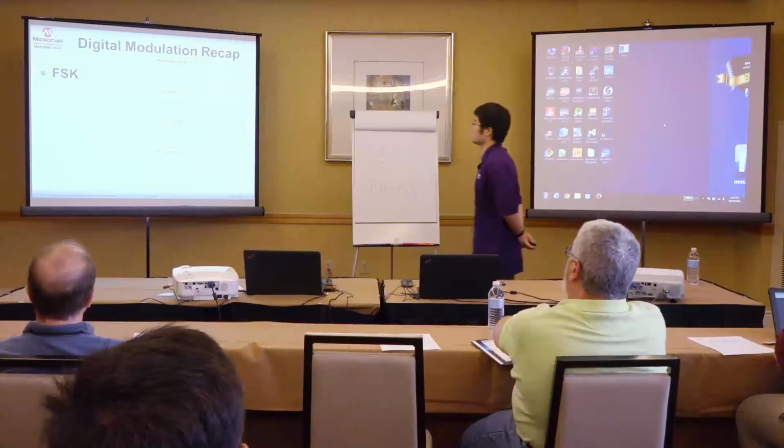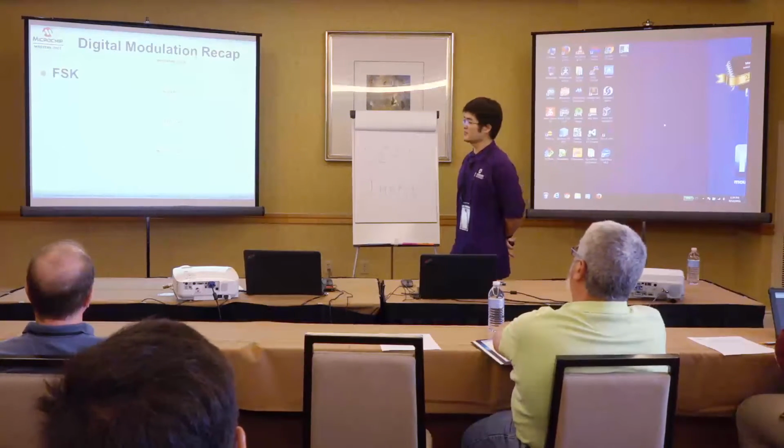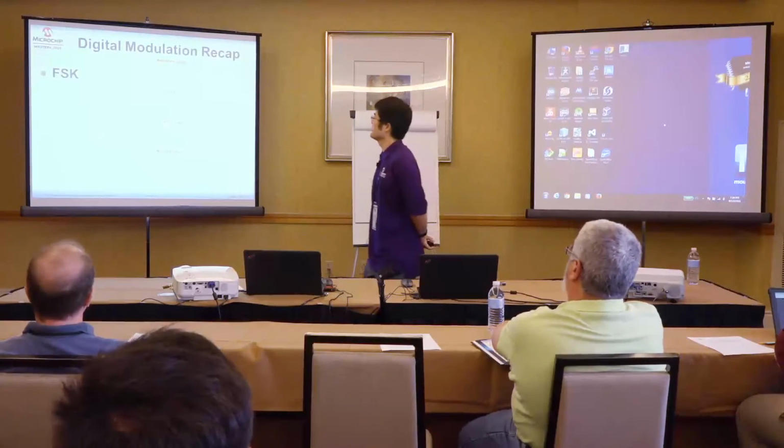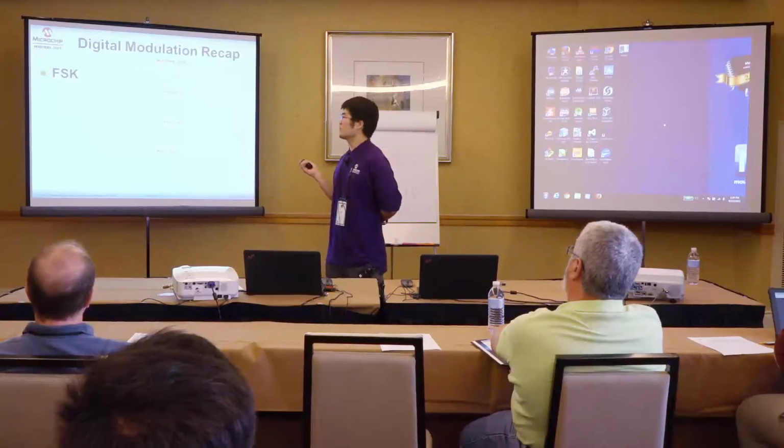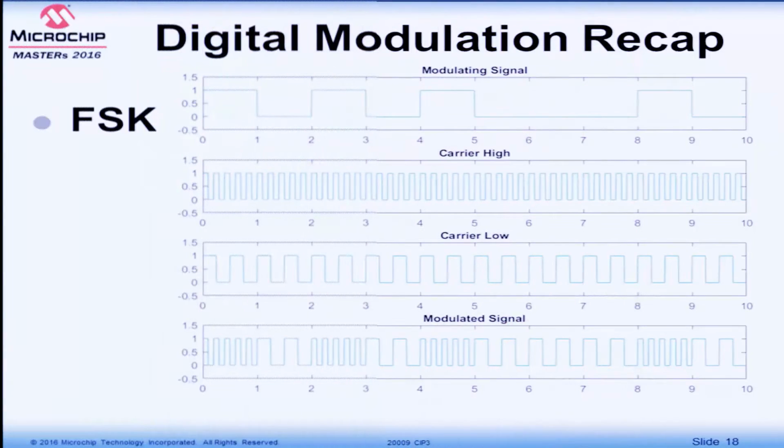The first one coming to our mind is probably FSK, just to refresh your memory. What we do with FSK is we have a modulating signal, that's your original signal. You can pick 2 different frequencies for your carriers. You have carrier high and carrier low. You modulate your modulating signal onto those different carriers depending on whether it's logic 1 or logic 0, and you get your output. When it's logic 1, it might be a higher frequency. When it's logic 0, it might be a lower frequency, right?